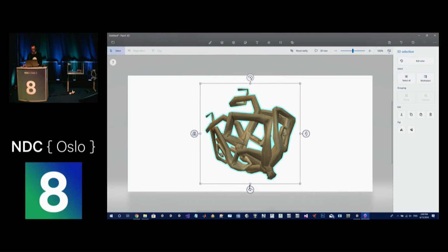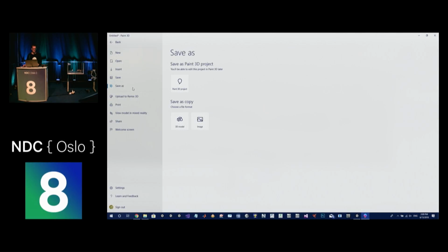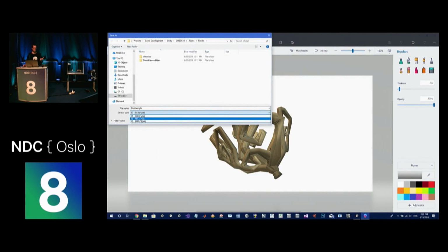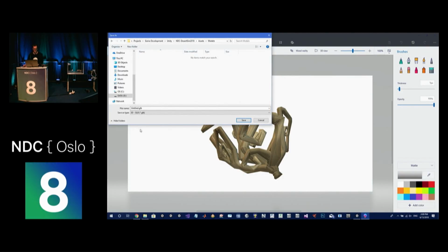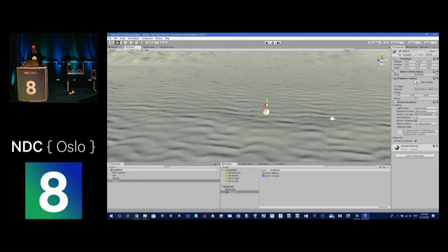As you can see, this is a full 3D model, all in Paint 3D. You can even draw on it and add some textures if you want. Then I can select Menu, and then save as a 3D model. Unity understands the 3D FBX format. So I'm going to go in here and add this to my project, the Desert Sim. I'm going to add models. There we go. Then make sure FBX is selected. It can be named Untitled, it's fine. It's an Untitled Tumbleweed.